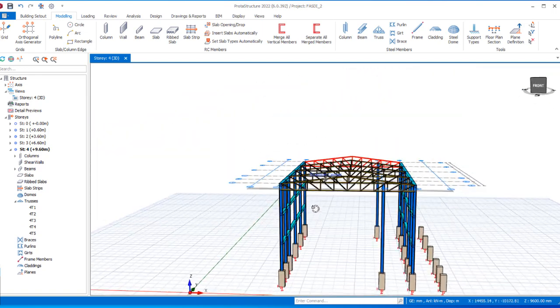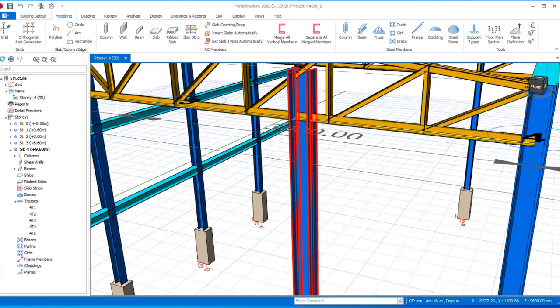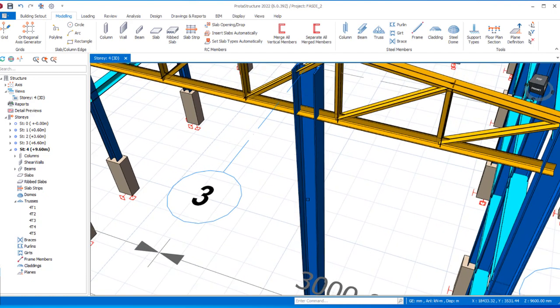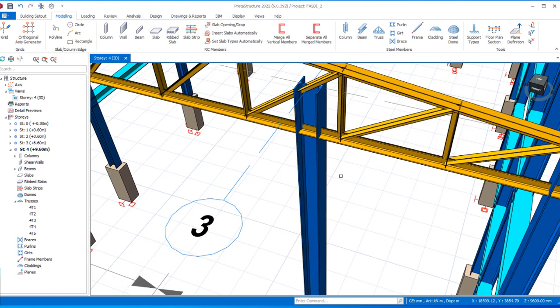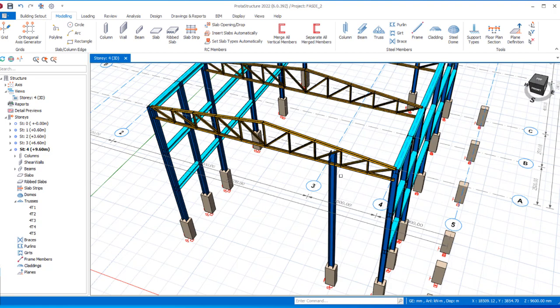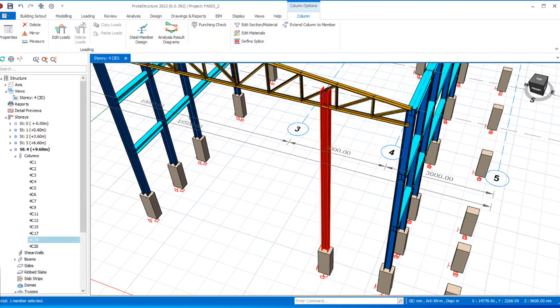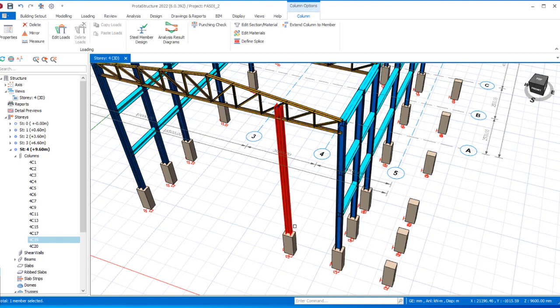All right, so having placed the trusses successfully, the next thing, if you check very well, you will notice that this particular truss is actually clashing with the stanchions right there. So for us to adjust the stanchions to be directly under the truss, we will have to do that effectively. But this stanchion is not actually carrying the truss, as you can see. So we may not necessarily use these sections for this truss. We want to change from these sections.